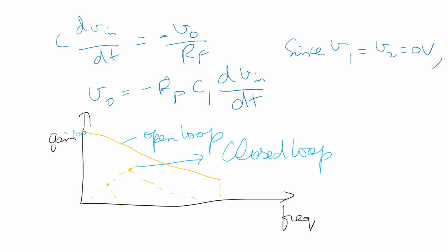The gain limiting frequency FB is 1 by 2 pi R1 C1. R1 C1 is equal to RF CF. They help to reduce significantly the effect of high frequency input, amplifier noise, and offsets. Above all, it makes the circuit more stable by preventing the increase in gain with frequency.